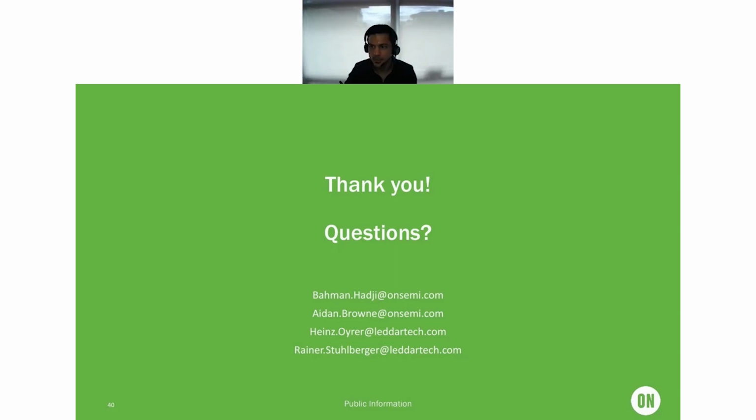Thanks, Aidan. And then just on the crosstalk, crosstalk is a phenomenon where you can have a certain number of microcells triggering due to photons generated within the SiPM itself. We do provide a spec on that.